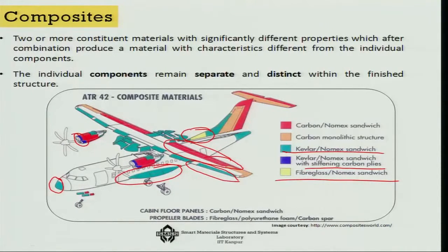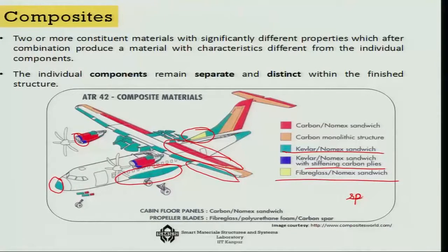So, one of the two advantages that composites give us is in terms of lightness, and in terms of strength and modulus of elasticity. We actually say this in terms of specific stiffness, which means modulus of elasticity per unit density, and specific strength. That means, once again with respect to the weight, the stiffness or the strength that you get is very high in composites.